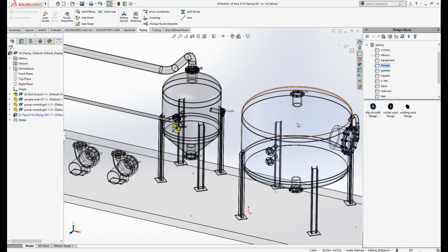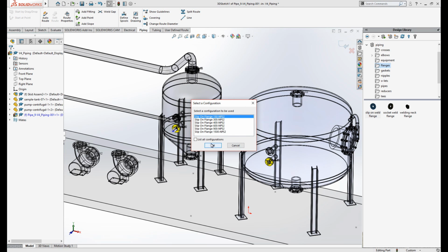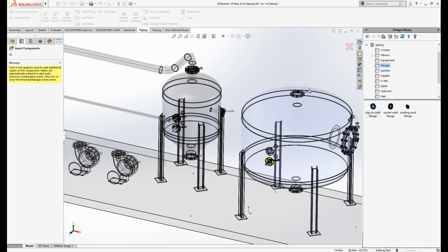And now we are going to select another flange where we wish our pipe segment to end. Now if you notice, on both flanges, we have a pipe segment sticking out. This is where we will begin and end our piping. Also notice, we still have the flange on our clicker, so we can place another flange if we wish to have our pipe connect in multiple places.